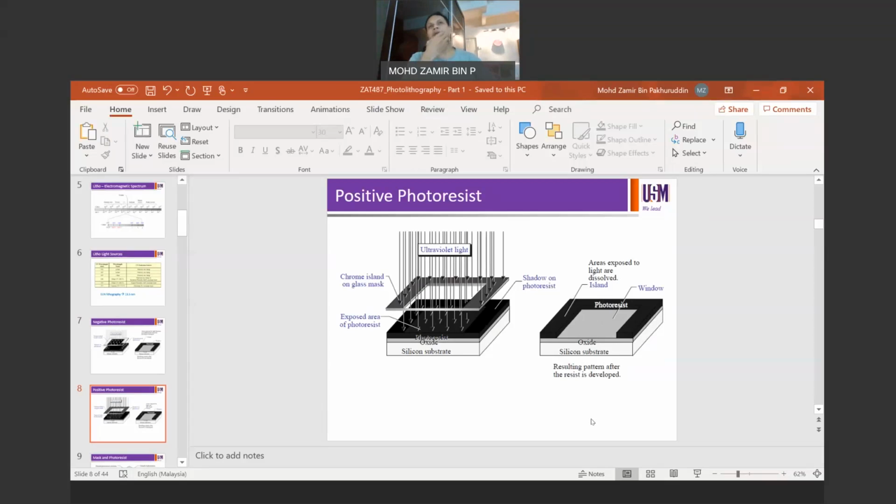So to be able to run your lithography process, it depends on whether you are using positive resist or negative resist, and the reticle can be set up like the previous page where you block the light in the central region, or on the other hand, you can also allow the light to pass through the central region. What you're going to have is basically opposite structures.